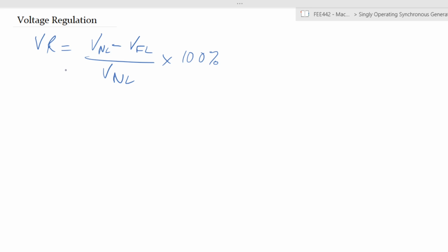And so on and so forth. So for purposes of this discussion, we will say internal resistance, or the resistance of the armature windings, is roughly 0. So, to simplify the calculations a bit, we will only be considering the property of synchronous reactance.